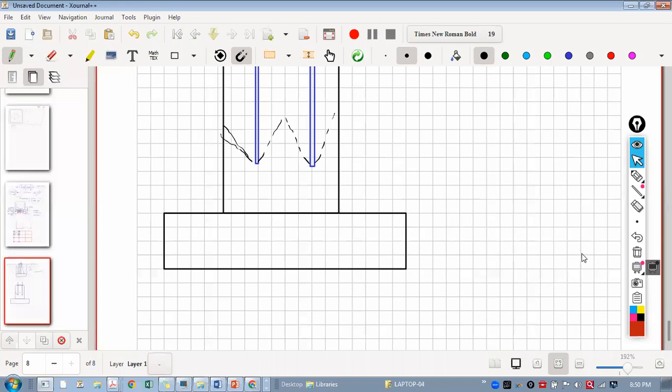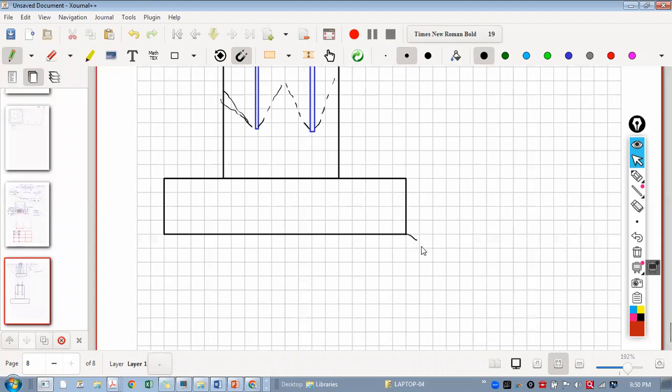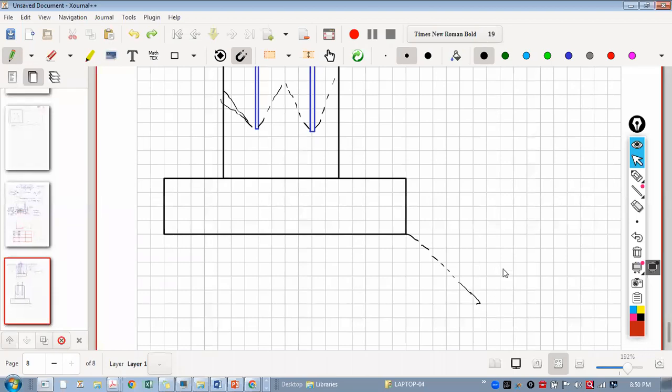Yes. Now let's say I have a footing on one side, then this is your failure plane. So your footing should not come here like this. Let's say we are having footing levels different. Sometimes it may happen. Then this failure plane should not cross through this. Otherwise, whatever load is here, part of the load will go on this footing. That is why we need to take horizontal and vertical distance the same. So in this case, let's say this is your failure plane, then I will provide the footing at this location.